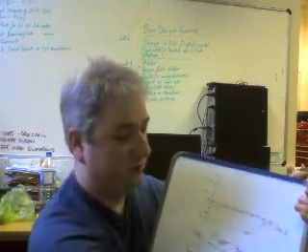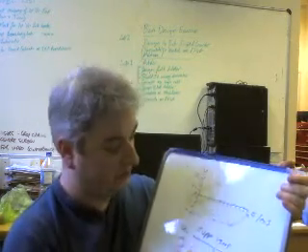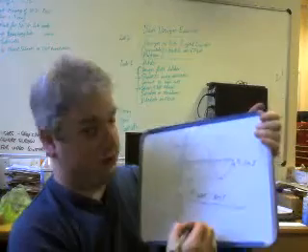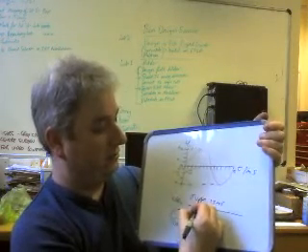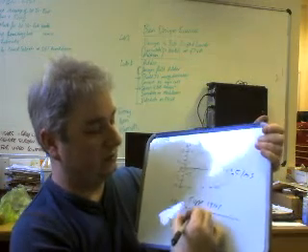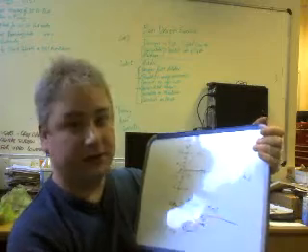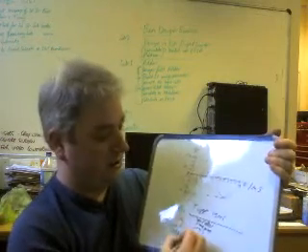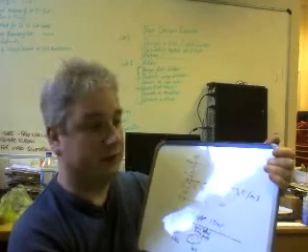On the oscilloscope, there is a knob with time written on it. There's another knob over here with seconds per division, or sometimes it's referred to as the time base, and it would be represented as 1 millisecond.